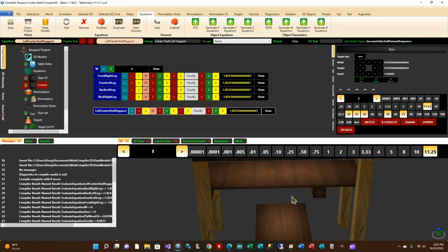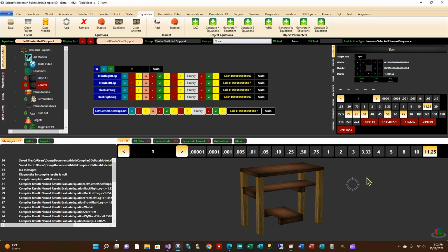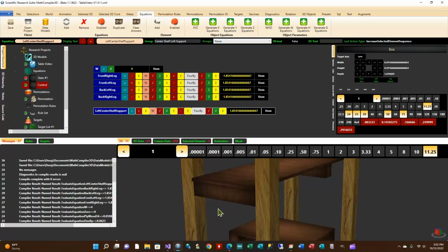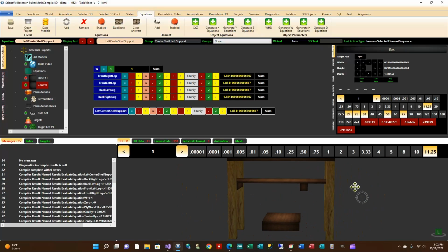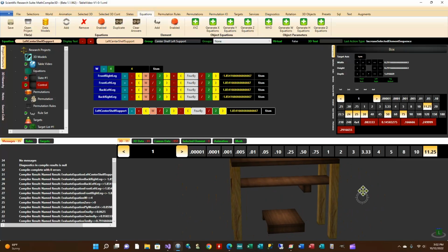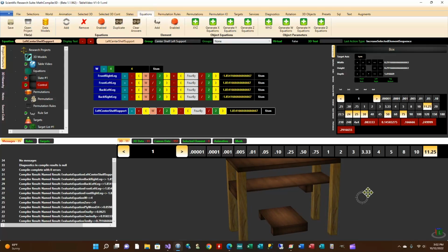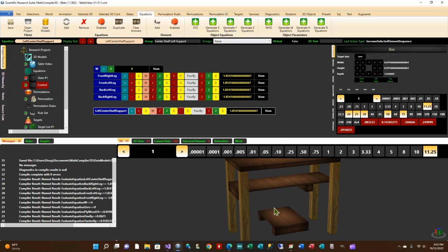And then switch back over to 3D. And now I'll go ahead and zoom in. And as we hit F6, then it pops right back into where it should be. So once in a while that happens. Always double check a drawing and see what state it's in before you start. And worst case scenario, you can do what we just did, diagnose the problem and fix it.